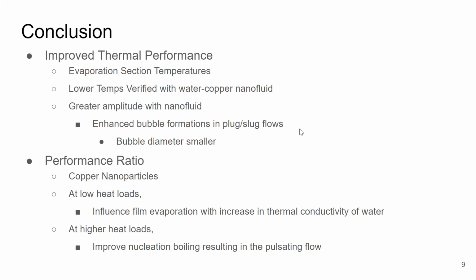And also, based on the performance ratio for the copper nanoparticles, we saw at low heat loads, the film evaporation was more dominant based on the increase in thermal conductivity of water. And for the higher heat loads, when the heat increased, the nucleation boiling took over the pulsation flow.